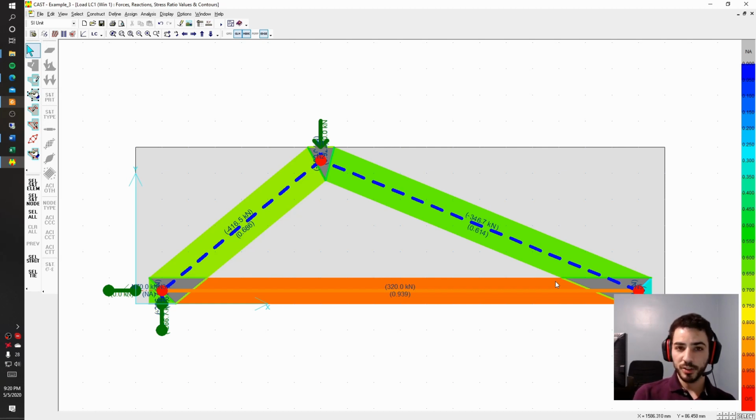It can be used for slender beams as well, but it is more effective if the beam is deep. And if you need to use a very shallow strut with a very shallow angle, usually it might mean that that element is not that deep, so you should not be using strut-and-tie as much. So that's why that clause is over there. But that's also to illustrate that if you have such a shallow element, it is likely that your stresses from your point application won't go exactly directly to your support here on the right.